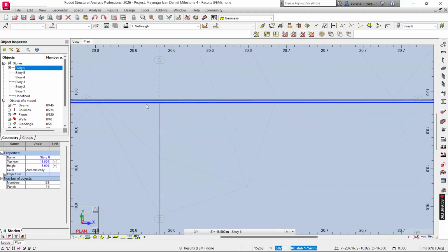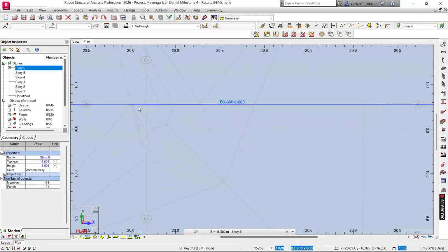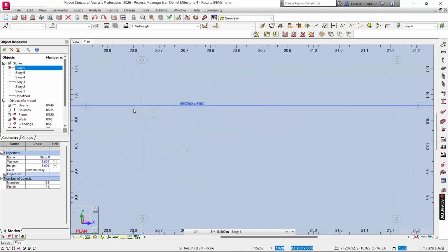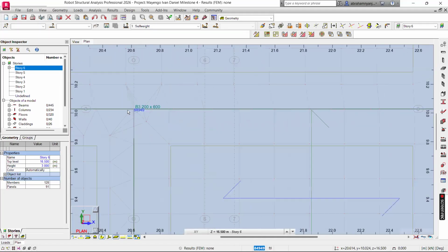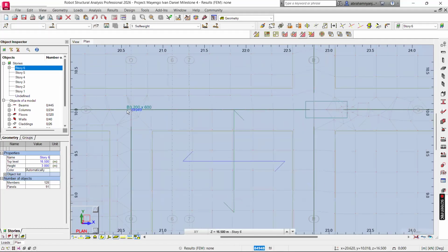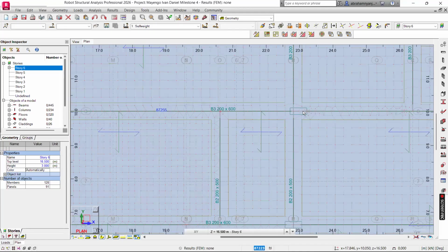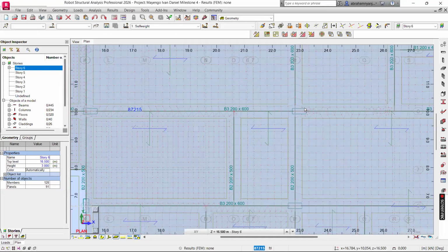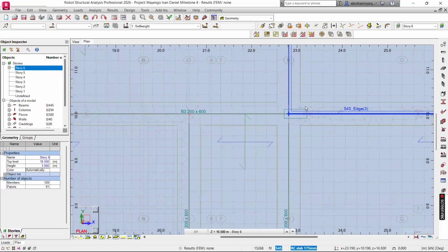Wherever you have meshing issues, one, you have to zoom in and try to identify exactly where you snapped to. Because as we noted, every point you snap to means a lot in Robot. We talked about the circle, the rhombus, and the triangle and what they mean, so that when your cursor turns into something, you know what you're snapping to.